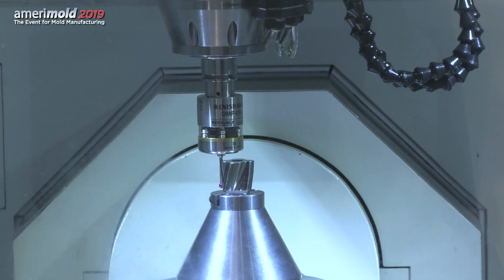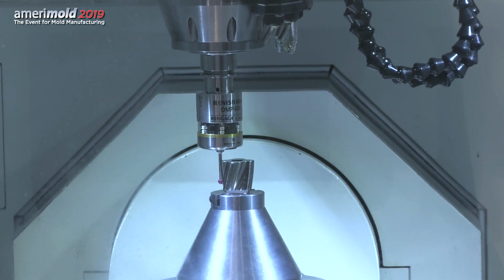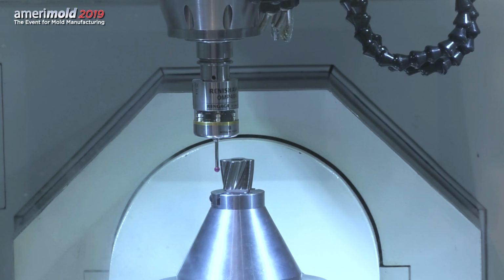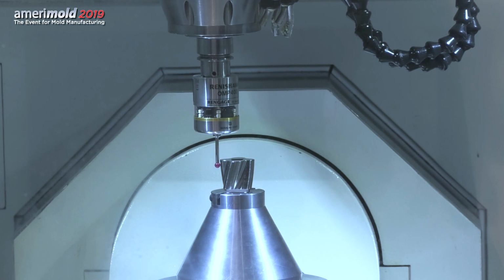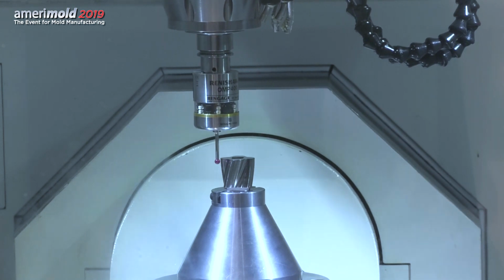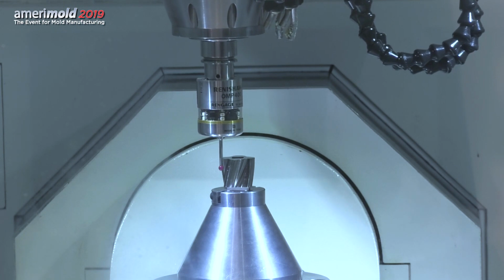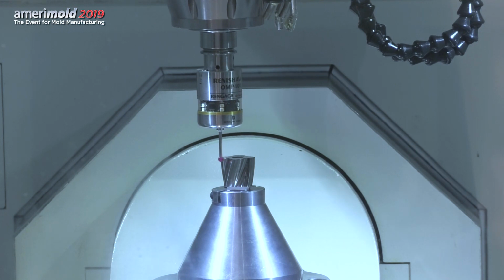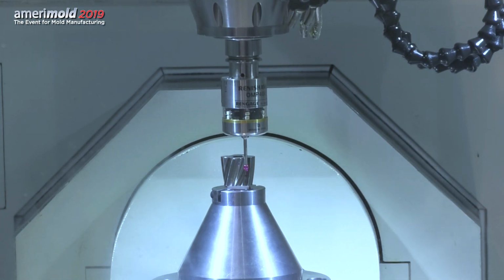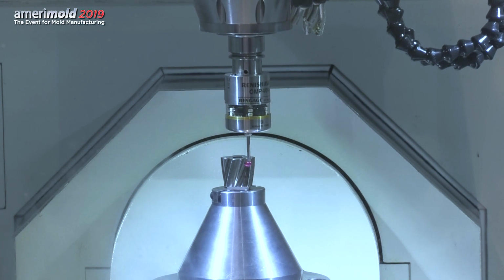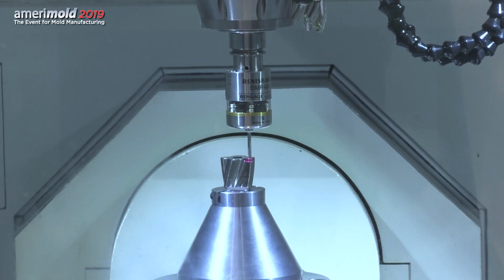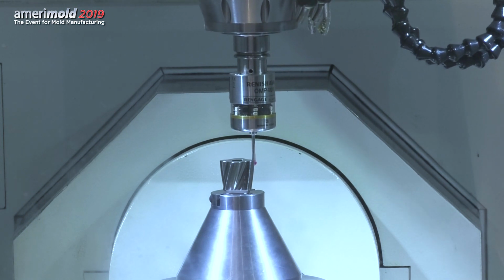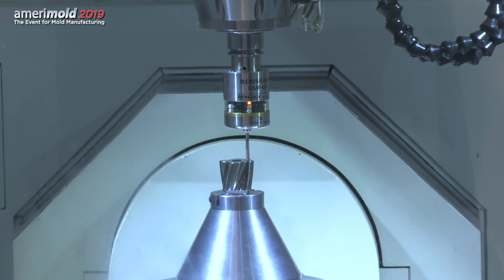Additionally, the machine is stable, it is repeatable to the point where we can demonstrate 1 to 14 diameter to length ratio on cutting tools. So for example, in the molds where we have that deep pocket that we need to get into, that we always relied on someone to do the final blending, we can reach those very deep pockets. Again, it goes back to the spindle design is our own, so we eliminate radial play, Z-axis extension, and it is repeatable.